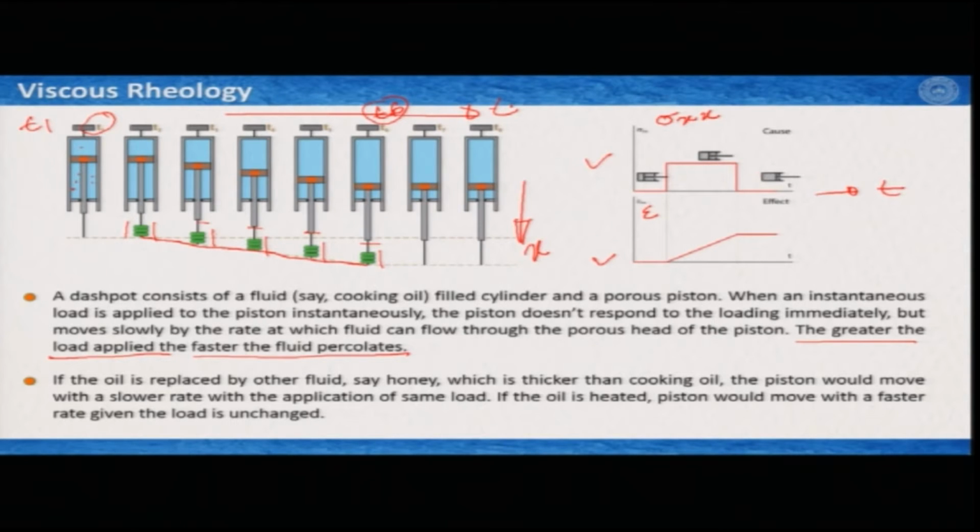So, what is happening at T1 time, there was no load. So, stress is 0, strain is 0, which is normal, which is expected. And now, an instantaneous load has been applied, these 4 bars, and we see that strain here is not instantaneous, but it is increasing slowly. So, you applied the load and kept it for a while.